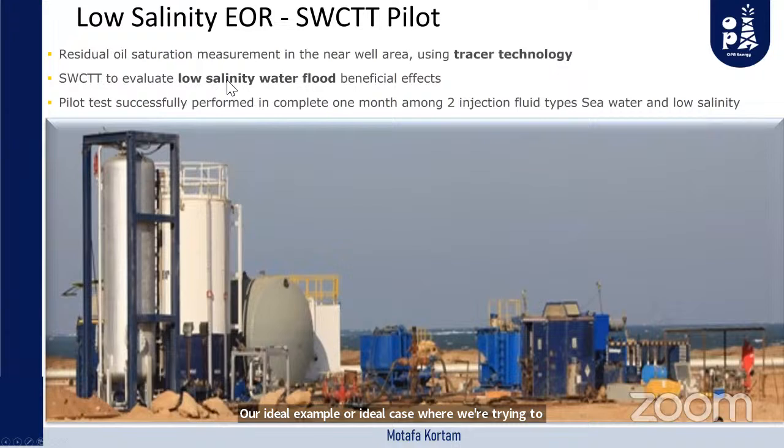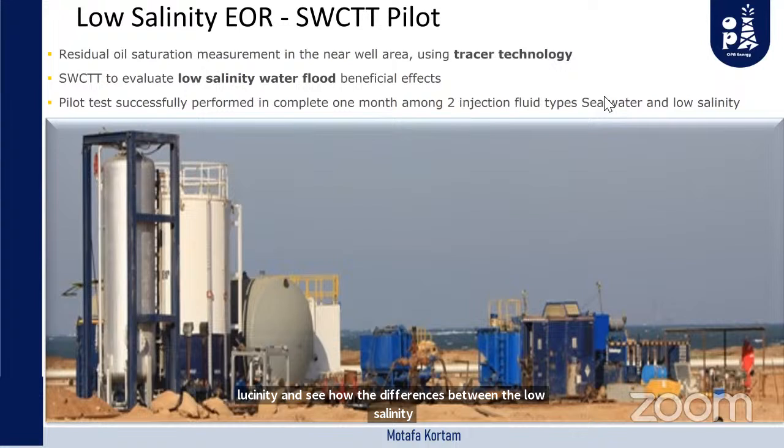We also wanted to investigate the potential of low salinity water flood and see what its beneficial effect is. We managed to do it through two injection fluid types. We injected seawater, then we injected low salinity water, and looked at the differences between them on the residual oil saturation, and whether the low salinity water reduces the residual oil compared to the seawater or not.